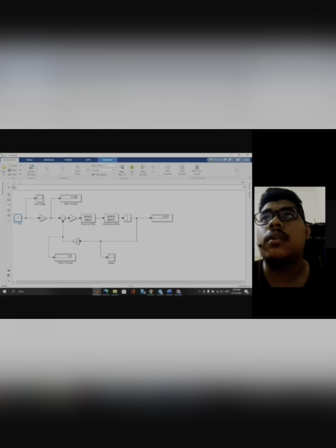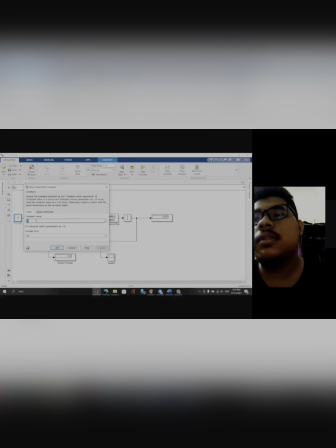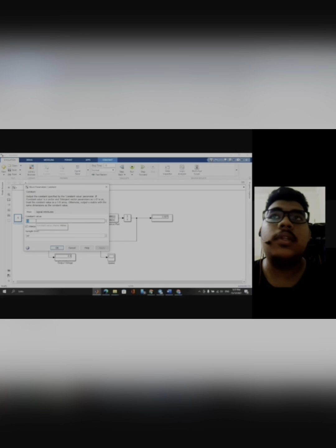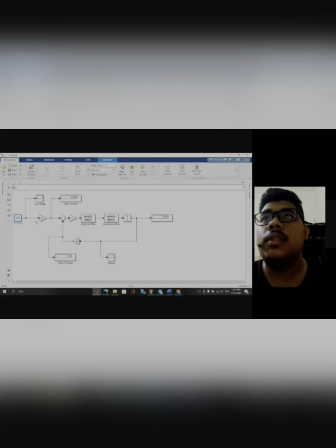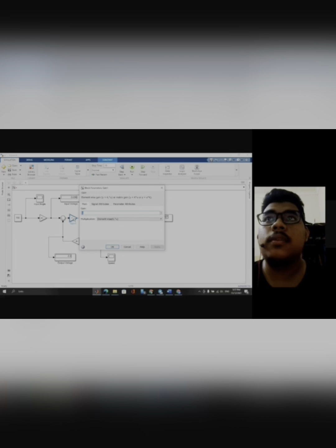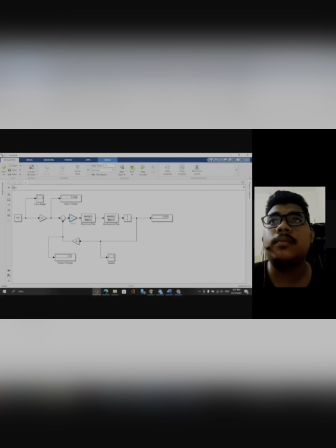Next, for the angle 150, and the attenuator gain is 5, I run the simulation. As you can see, the input voltage we get is 91.67. The output voltage is 84.61 volt, and the shaft position is 138.5 position clockwise.